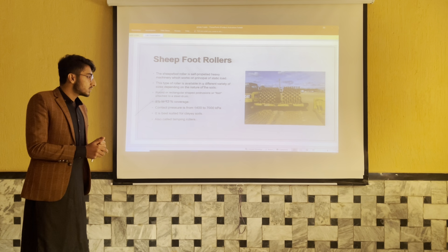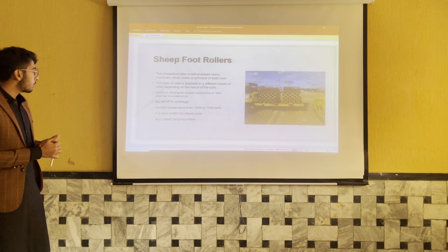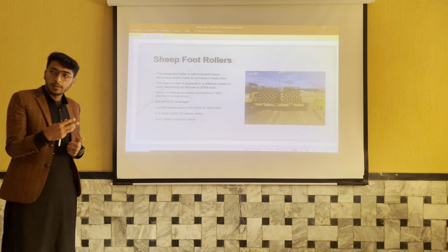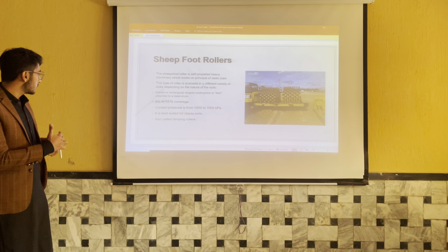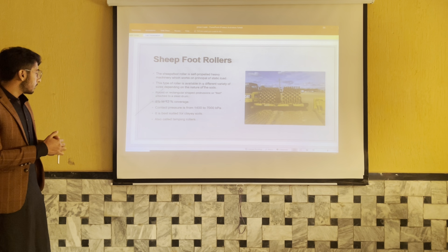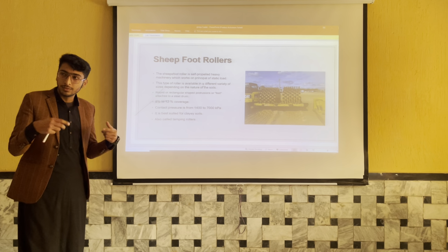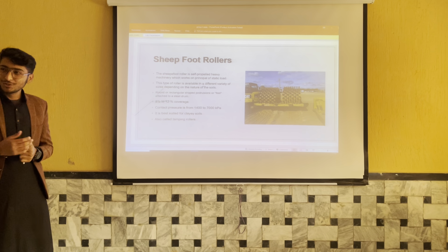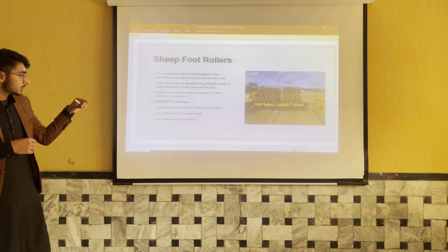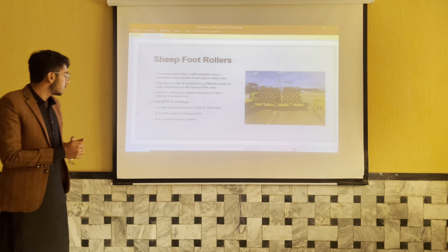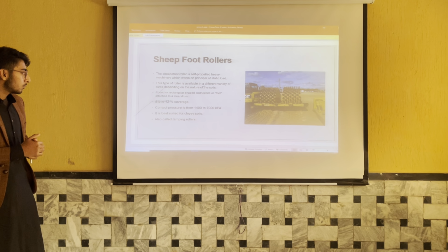Our next type of roller is the sheep foot roller. Sheep foot rollers are self-propelled heavy machinery rollers, meaning they work by their own, and this type of roller is available in a variety of sizes depending on the nature of the soils. Sometimes we have attached rollers, and sometimes we have sleeves of the rollers that we fit over the smooth rollers, and they cover 8 to 12% of the area over which they come.